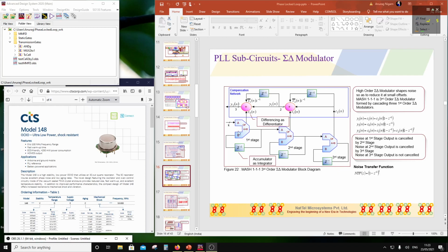That's why I'm not doing 16; I'm going to do a 12-bit Sigma Delta Modulator. So these accumulators are going to be 12 bits. Let's do a 1-bit accumulator, and then from there we go on to do a 12-bit.